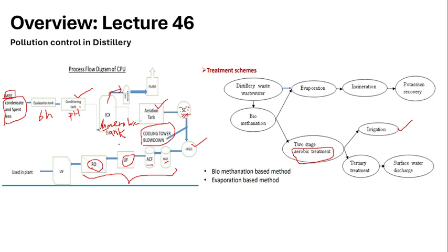By undergoing all these processes, now the water is completely clear water. Okay, and then finally they ensure its usage again. So we are using UV. So UV treatment is here. This is a tertiary treatment. Okay. After the UV treatment, we can reuse the water for the same plant, or we can check its conditions like BOD, COD, and all the other water quality parameters. Then we can allow it to discharge into the surface water itself. Okay. This is the process happening in the CPU.